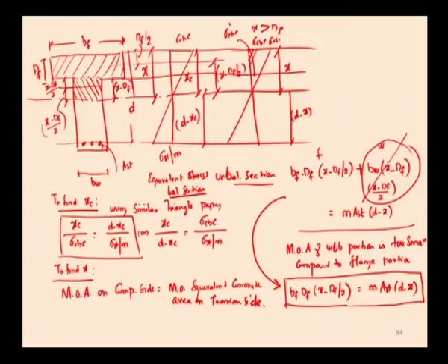So, here we have the stress diagram, here it is the trapezoidal one, and I am considering C to be the total compressive force offered by the compression zone, which is acting at the C G y bar from the topmost extreme fiber. So, here the stress diagram is a trapezoidal one. This is sigma C B C, this is sigma C B C dash. And the corresponding tensile force is taken as T, and the distance between these two forces is d minus y bar.